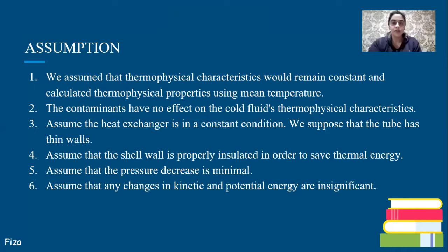For the calculations, certain assumptions are made. We assume that thermophysical characteristics remain constant and calculate thermophysical properties using mean temperature. The contaminants have no effect on the cold fluid's thermophysical characteristics. We assume the heat exchanger is in a steady condition. We suppose that the tube has thin walls. We assume that the shell wall is properly insulated in order to save thermal energy. We assume that the pressure decrease is minimal. We assume that any change in kinetic and potential energy is insignificant.